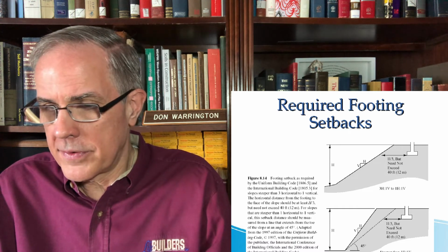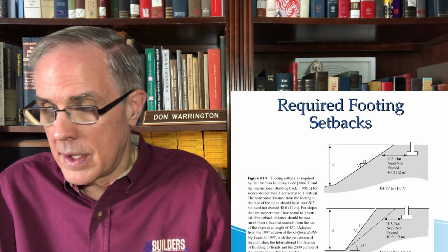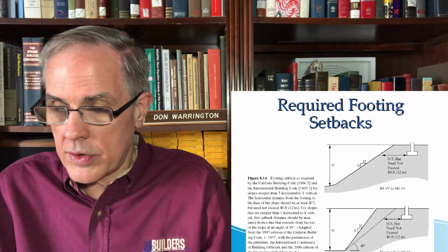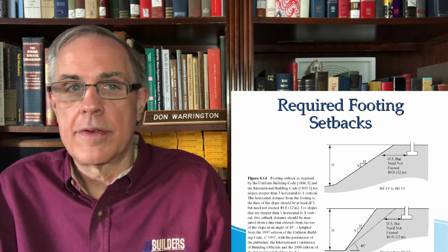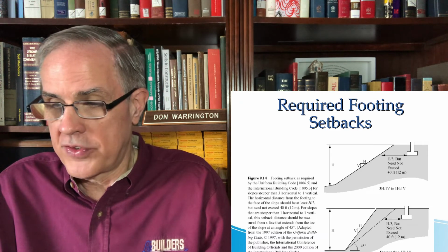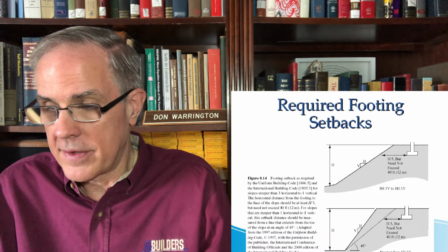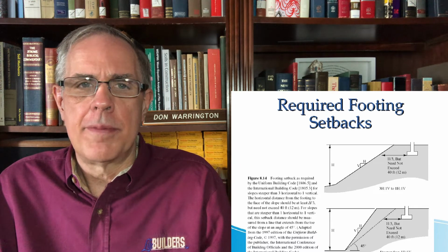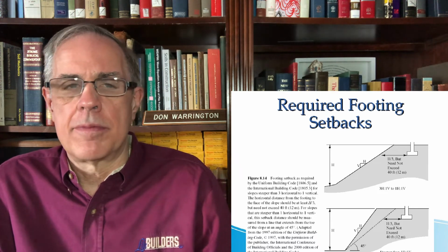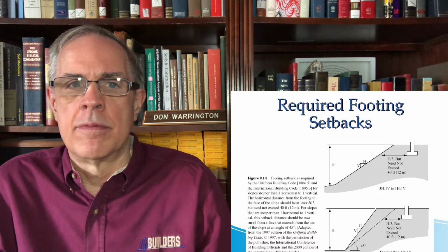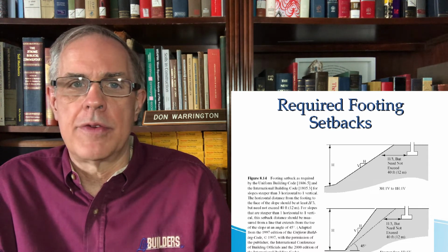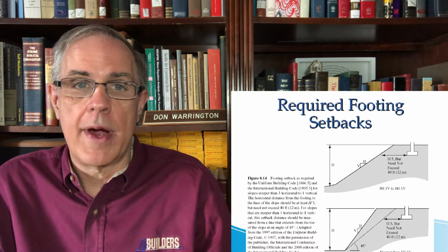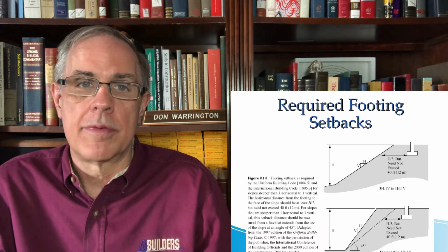Required footing setbacks. There are codes that exist that force a footing setback. That's a good idea. Slope stability is a complicated topic, as you saw originally, because just to get the slopes built without failure requires an iterative process.